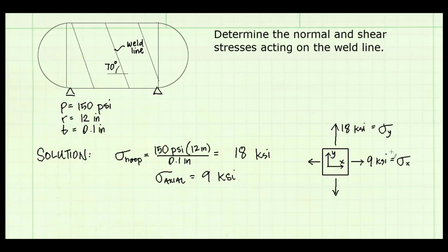Now I want to transform these stresses to the stresses that are acting on the weld line. There'll be a normal stress acting perpendicular to the weld and a shear stress acting parallel to the weld.